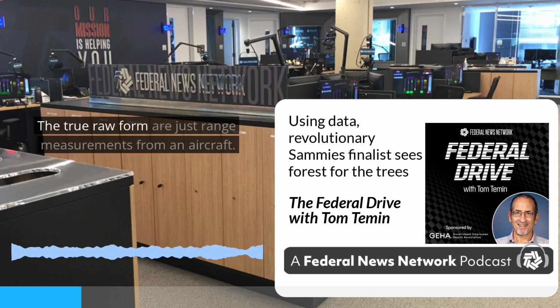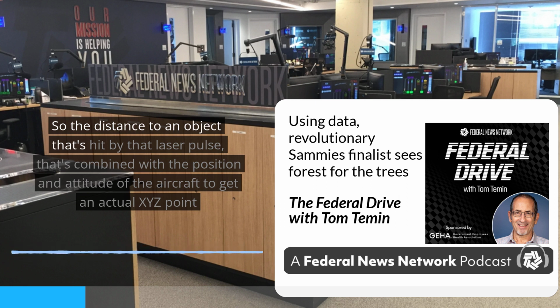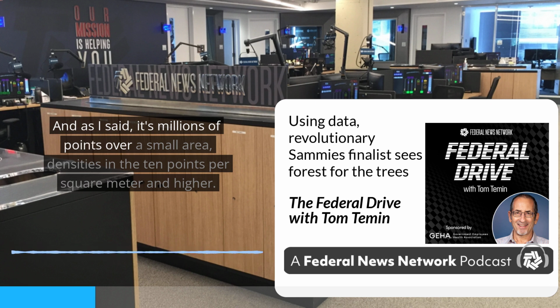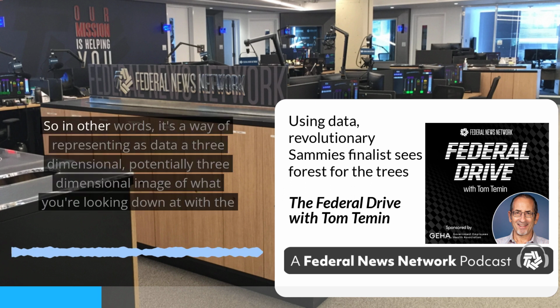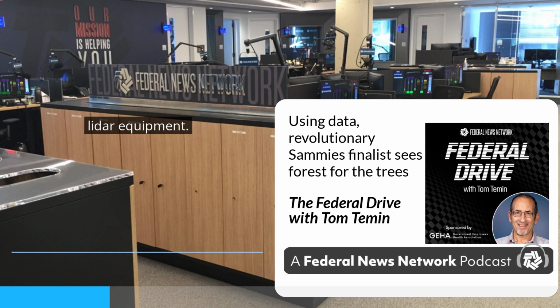The true raw form are just range measurements from an aircraft. So the distance to an object that's hit by that laser pulse. That's combined with the position and attitude of the aircraft to get an actual XYZ point for every object that's hit. And as I said, it's millions of points over a small area, densities in the 10 points per square meter and higher. So in other words, it's a way of representing as data a potentially three-dimensional image of what you're looking down at with the LiDAR equipment.